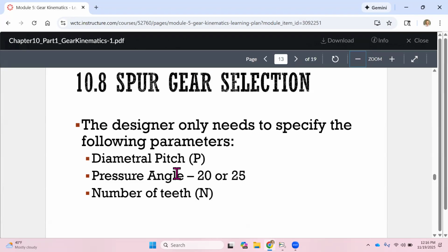Okay. Additionally, they have to have the same pressure angle. We talked about the pressure angles when we were together last time, and we did talk about it in terms of forces. I'm not going to repeat that, but remember there are 3. There's 20 degree and 25 degree. Those are the ones that we're going to specify for any new designs going forward. Okay. But out there are 14.5 degree pressure angles, and those are for service parts and maybe designs that you have to maintain out in the field. But anything new, you want to design with 20 or 25, okay?